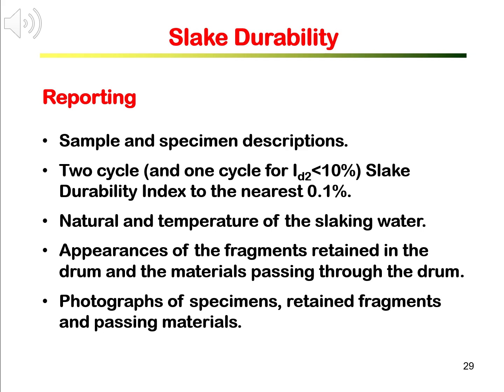Descriptions of fragments retained in the drums and the materials passing through the drum should also be reported and ideally photographed. Photographs of original samples, prepared specimens before testing, retained fragments in the drum, and the passing materials in the water should also be attached in the report.